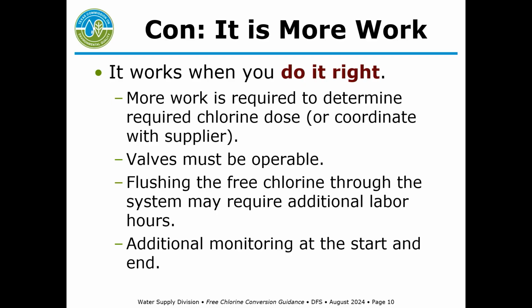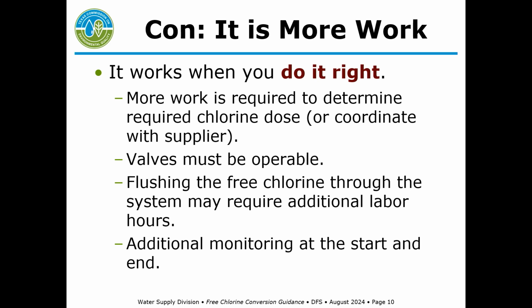Because it's possible you're going to have to increase your chlorine during the free chlorine conversion, so you're going to be using more. All your valves out in the distribution system need to be operable. And when you're flushing, as we'll talk about in more detail, that's just more time your operators have to spend. So just keep in mind, this is going to be a pretty time-intensive exercise. And then you've got the monitoring that you do at the start and the end of the conversion. Again, just added on to what the operators have to do.